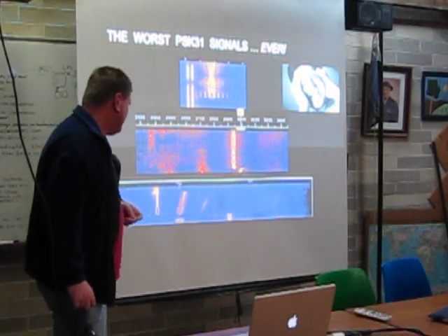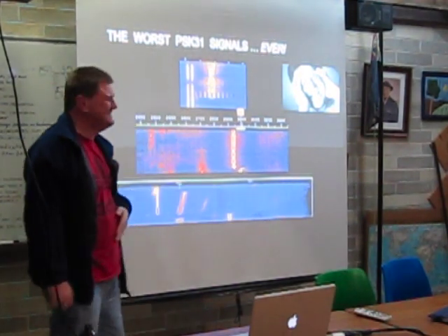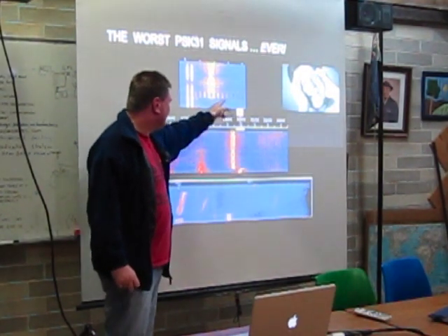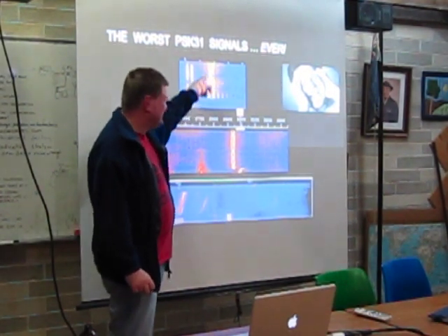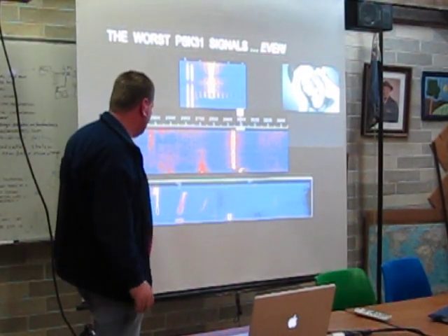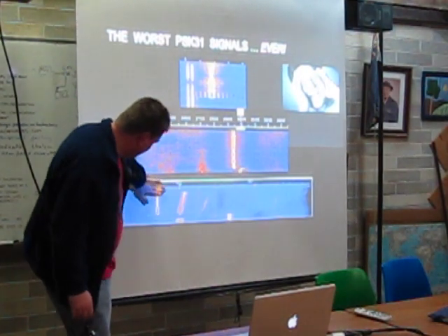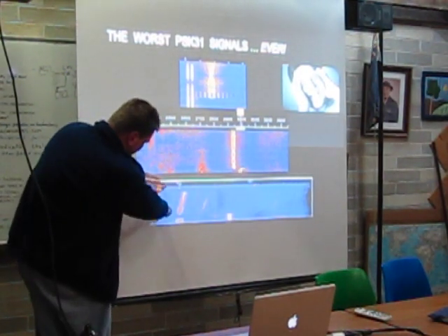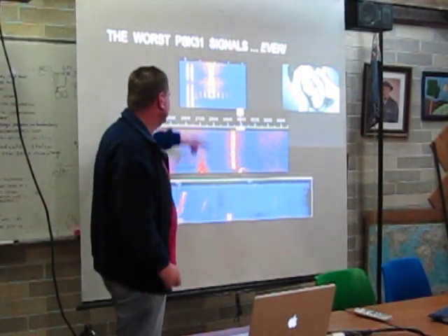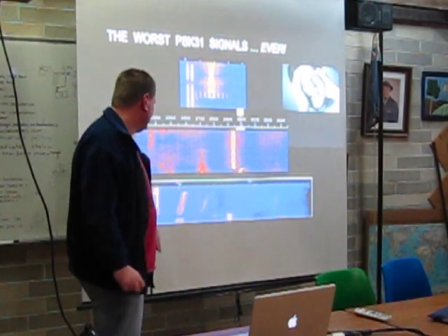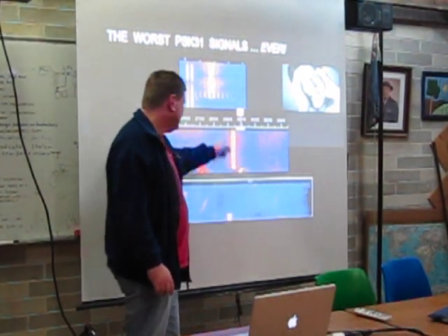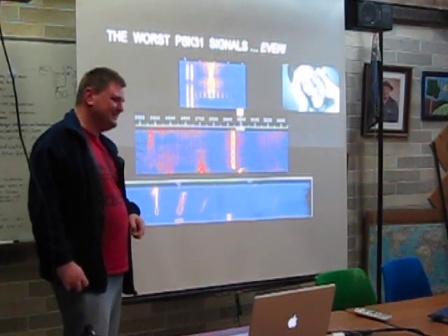If you do overdrive it, this is what happens. You can see here we're getting clipping, and so we're getting harmonics of the audio tones, and you get this. Normally a good PSK signal should be, that's a fairly reasonable one there. So it looks like the sort of railroad tracks. Here it's completely overdriven, so it's very wide like that. This one here is another bad one. See all the different copies you've got, that's all copies of that same signal.